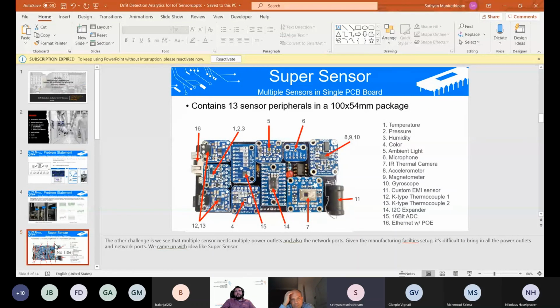Yeah, I think that's a good thing. That's what we also looked at, because if you look at these sensors, it's all piping to the same channel, right? Some of the sensors have high frequency bandwidth and generate a huge amount of data, right? If you take the thermal camera, the density of data that comes in from the sensors is very high. So for that, we have 2 channels coming from this data. We grouped low frequency and high frequency sensors as 2 sets of sensors. We don't want to mingle those sensors.